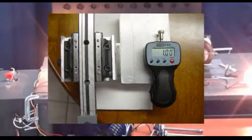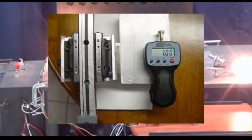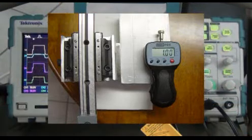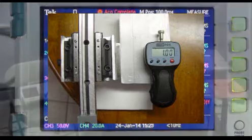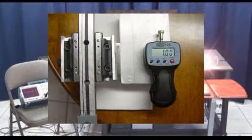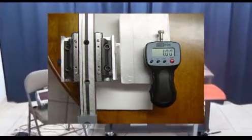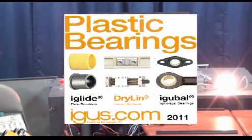Also, you see a weight force gauge displaying 1.00 pounds. This is how much force it takes to push the slide through the bearing with magnets attached. 6.7 times more force due to the magnetism transferred to the bearing and slide from the magnets. I have what I feel would be a good fix for this situation: plastic bearings with hardened aluminum rods.